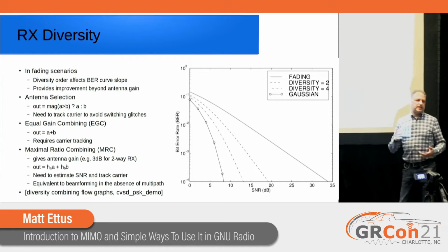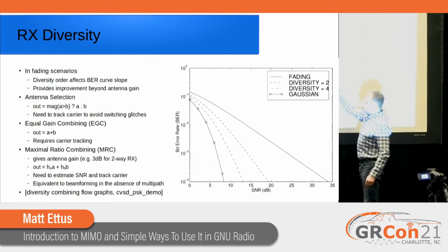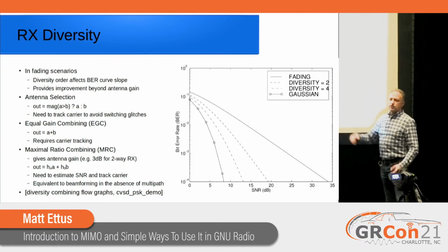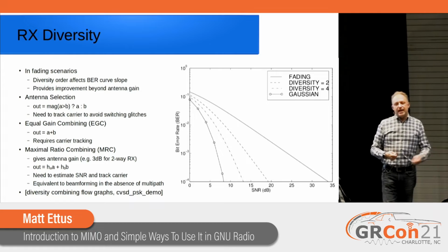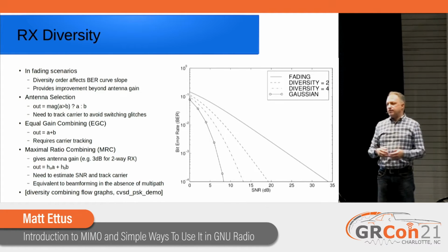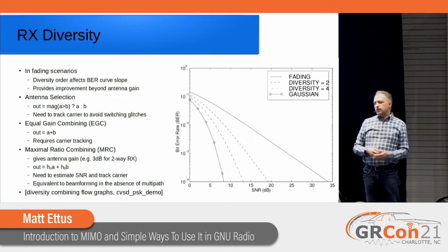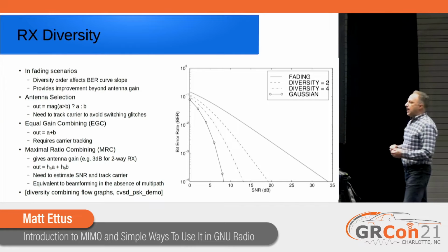And now why is that? We're basically saying that whereas before 1 dB could give you a huge drop off, now it takes many dB to get the same kind of drop off. So why is that? Well, if you have fades of 30 dB that are 5% of the time, let's say, adding 1 dB means maybe you'll have those fades 4.9% of the time, right? You won't get the same advantage.